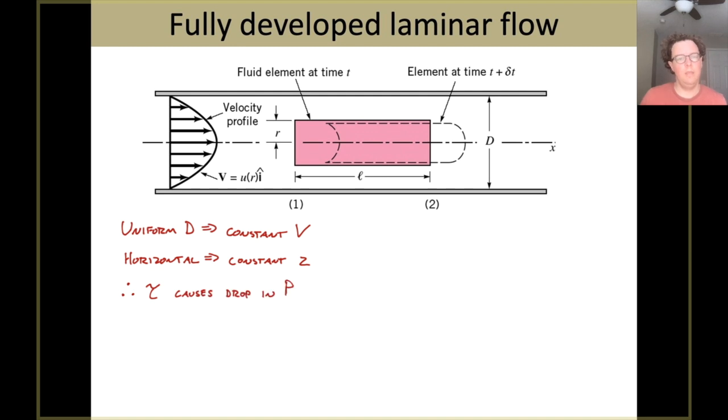What that means is that shear stress in the pipe, or friction within the pipe, is going to cause a drop in pressure. This is very parallel to the way that, when we talk about turbomachinery like pumps, they don't add velocity, they don't accelerate the fluid, and they don't often make a large change in the elevation head. Pumps change the pressure. Turbines lower the pressure.